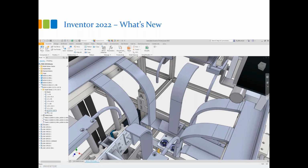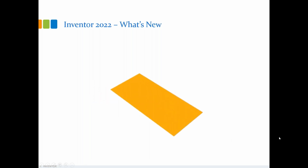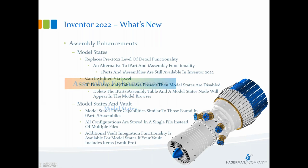So this instance here, this is in an assembly. We're pulling from one instance of a sheet metal component there where the angle that's being rolled around can be a 45, can be a 90. Everything is controlled there in one file, and we're just working through it as we go. Now, because we've looked at it on the part side, it's also got some love on the assembly side. Now, this does replace the level of details. So if you create a new assembly inside Inventor 2022 using the 2022 templates, there is no level of detail. It is no longer there. It's not available.